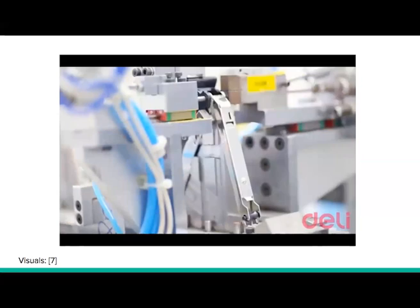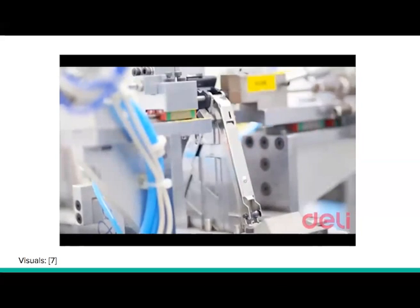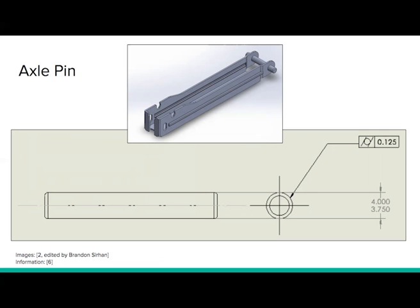To ensure this, the tolerances for the axle pin diameter were determined by taking into account the tolerances we chose on the bottom housing pinhole. By choosing the tolerance of the diameter of the axle pin to be 0.25 millimeters, specifying the lower limit to be 3.75 millimeters, and the upper limit to be 4 millimeters, we ensure that the pin can always mate with the pinhole. Following GD&T guidelines, the maximum radial envelope, in this case the pin diameter tolerance boundaries, cannot exceed your maximum diameter tolerance.